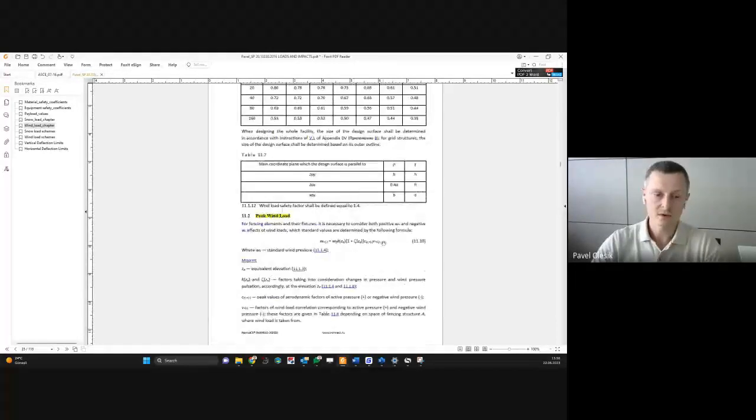I think I calculate only fencing structures and check, yes, I also usually check corrugated sheet for this load. I'm checking base load separately and peak load separately, not base plus peak load. And I'm choosing the biggest value and calculating on this value for corrugated sheet and sandwich panels as well.